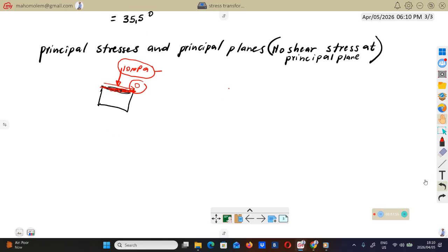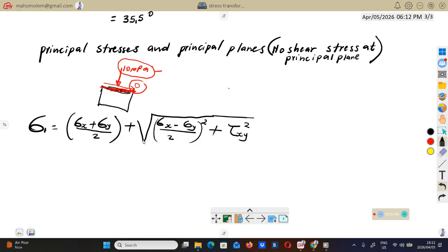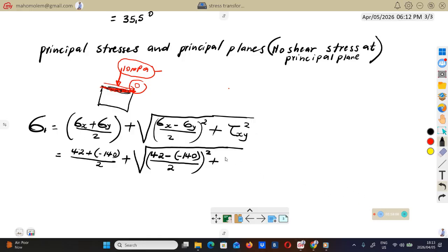So I'm going to write the formula down. Substitute. We know why the shear stress is negative. Even though normally this one, negative or positive, won't have an effect since we're going to square it, always put that negative if it's a negative shear stress to show that you understand.